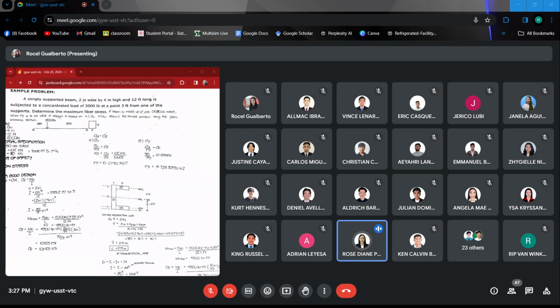Then based naman po sa yield strength, same ang formula: factor of safety is equal to sigma y over flexural stress, which is equal to 58 KSI over 10.125 KSI, is equal to 5.728395062. Yun lang po, ma'am. Okay, thank you, Miss Rose.